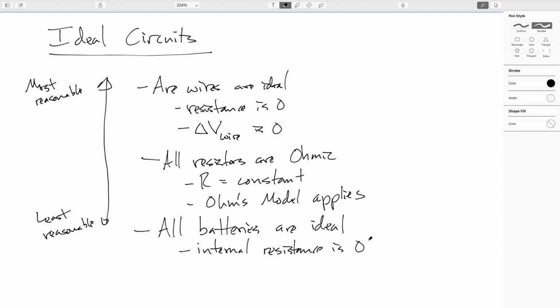This is, in fact, an issue that some manufacturers did discover early on, but at this point, everyone has learned their lesson, and they go to the effort of liquid cooling their batteries so that they can stay within desirable temperatures from a chemical point of view. So, you have to worry about the internal resistance of the battery.